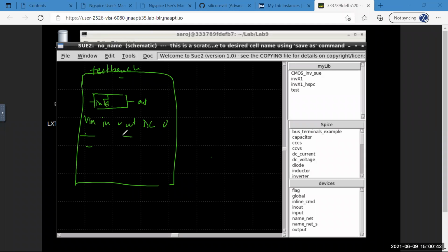Now, even this you can do in SPICE, but avoid doing that for now. That is for when you start doing a little bit more simulation, because this is a good practice, and it allows you to use any SPICE function. If you use the schematic, there are only a few blocks like the voltage source, current source, and so on. Whereas if you use this, then you pretty much can use the entire NGSPICE command set.